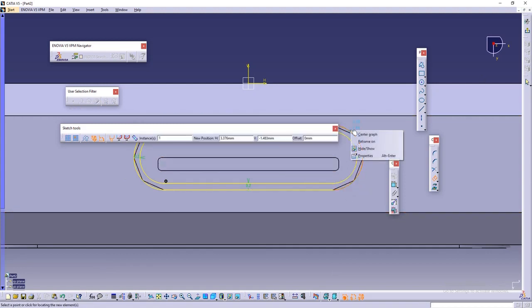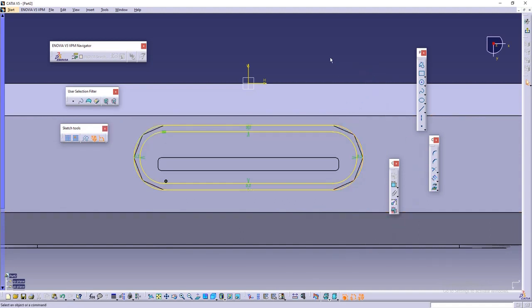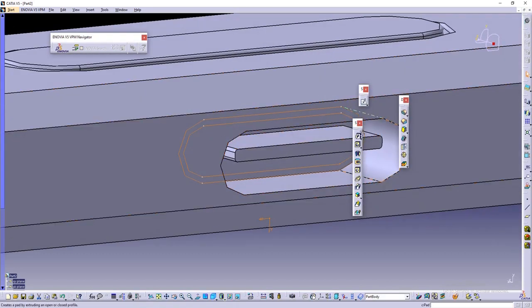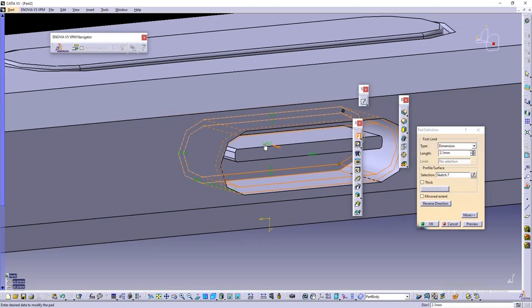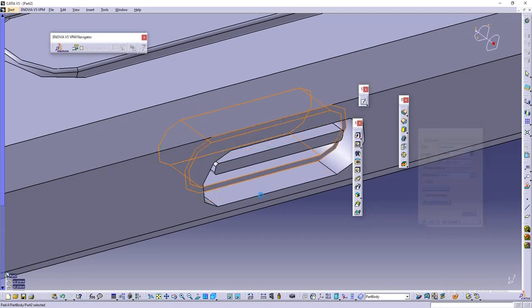Then we can just double click here, so it is deselected, click outside. Now I don't want this, so I can just delete this thing, right? Or maybe I can keep this thing, Control Z undo, because we just want to create a small detail over here. So go back, and then you can just go to pad, again reverse the direction, and then it is written 1.5, preview, and then okay.